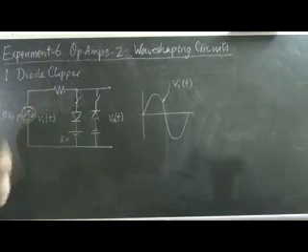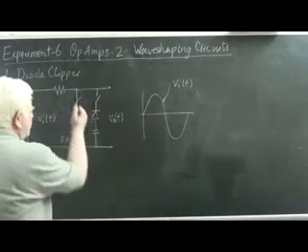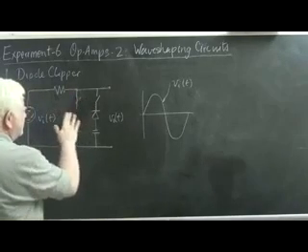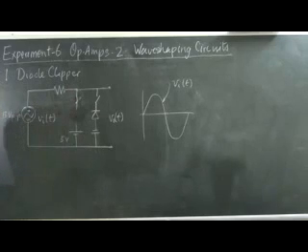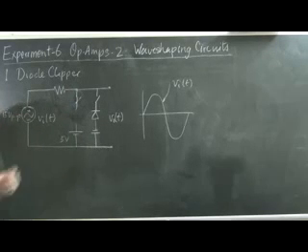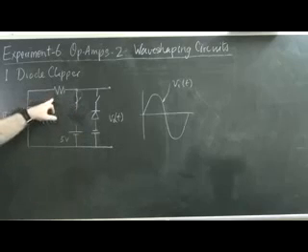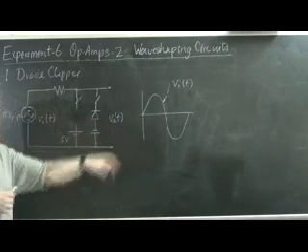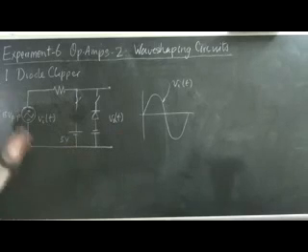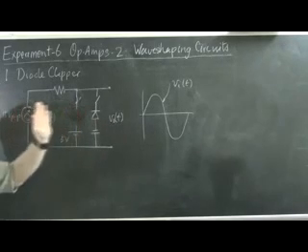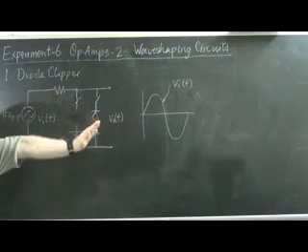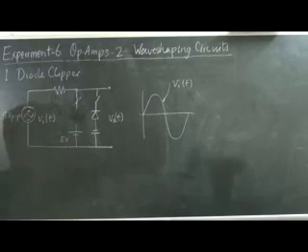So the equivalent model of this circuit will be what you would see if you didn't have this diode, just this. So whatever input signal voltage is applied merely appears at the output with a voltage drop on this resistor only if this output is loaded. Otherwise, it is a 1:1 relationship between the VO of t and the VI of t.